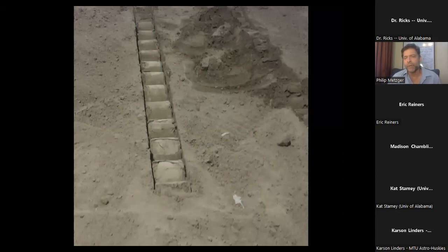But see, what this wheel did was, instead of shearing the soil and fluffing it as it drove, it compacted the soil. It had these inwardly curved surfaces with spikes. So as it drove, it compacted the soil, and then the spike would push off of the freshly compacted barrel of soil that it had just compacted in place. So it strengthens the soil and uses that to get torque or traction. So that was a pretty innovative design.